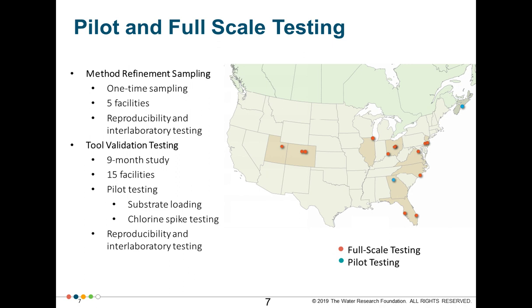The nice thing about incorporating 2 piloting facilities was that we were able to conduct some specific controlled experiments that might not lend themselves quite as well to a full-scale facility. Here we looked at one test, which was to enhance microbial activity by intentionally adding additional biodegradable substrate over a specific duration of time. The second experiment that we conducted was to intentionally attenuate bioactivity by adding a disinfectant to the filter influent. The objective of conducting these experiments was to evaluate the response of our monitoring tools to these changing conditions that we were modifying on the filters.